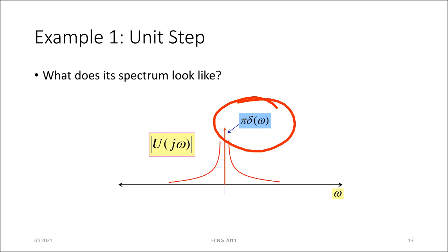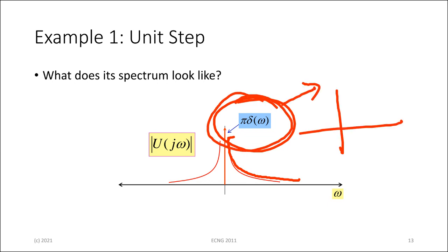In frequency, you put an impulse at omega equal to 0. That's a DC, a sudden DC impulse that you give the system. And of course, you have some frequencies that start from very low and deteriorate as you go up here. So again, it's a very incredible test on the system. This impulse here also is part of the reason why systems tend to oscillate if they're not controlled when you give them a step input, at least the higher order systems. Making sense?